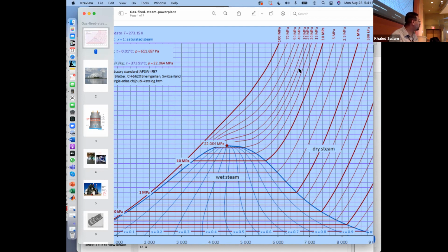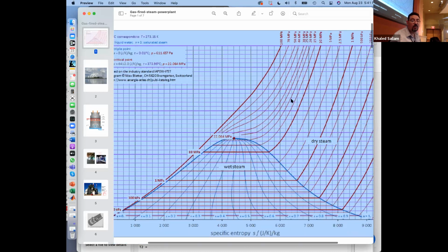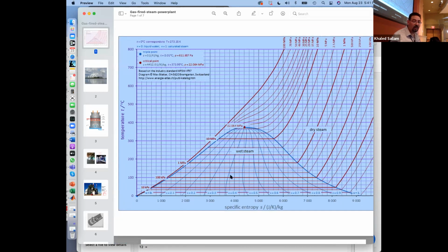So the first part of your project is to investigate how high we should get. Imagine a regular steam power plant going like this, and then I'm asking you, what pressure should I run at? Find out what's best. You want to run the calculation for what if it's 10 bar? What's 22? What if 30? What if it's 40? As you take the pressure up, I want you to keep calculating the efficiency, and then put them in a nice table and say, wow, here is the maximum efficiency, and that can be achieved at that pressure.